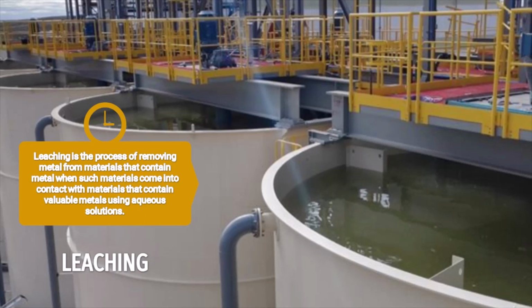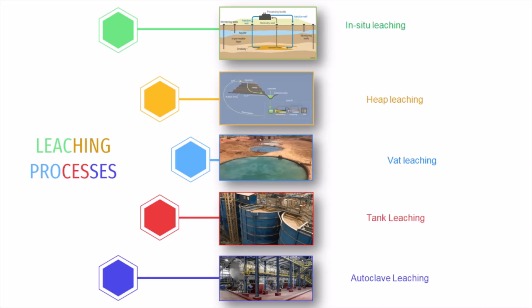So we'll kickstart with the leaching process, which is perhaps the most important stage in the hydrometallurgical cycle, as without it we will not be able to go forward with the actual extraction of the minerals. It is basically a process of removing the valuable metal from materials that contain it, using aqueous solutions. Of importance is to note that in leaching, mainly it's aqueous solutions that are used.